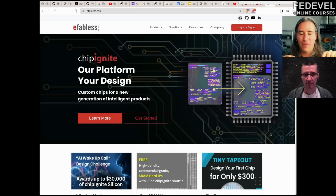Caravel was like a pad frame with a little RISC processor and stuff like that. So that has the pad ring and the logic analyzer and things like that. And so Tiny Tapeout was in the user project area. And that kept on going for a little while. Then Sylvain Minot, TNT, did the MUX, so he's involved in that, but it was still in Caravel. Now Caravel is gone. We're using the open frame pad ring.